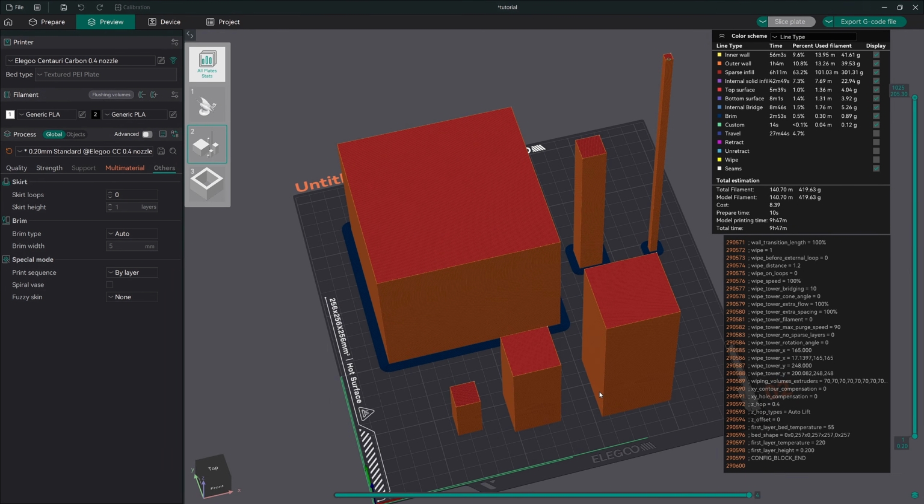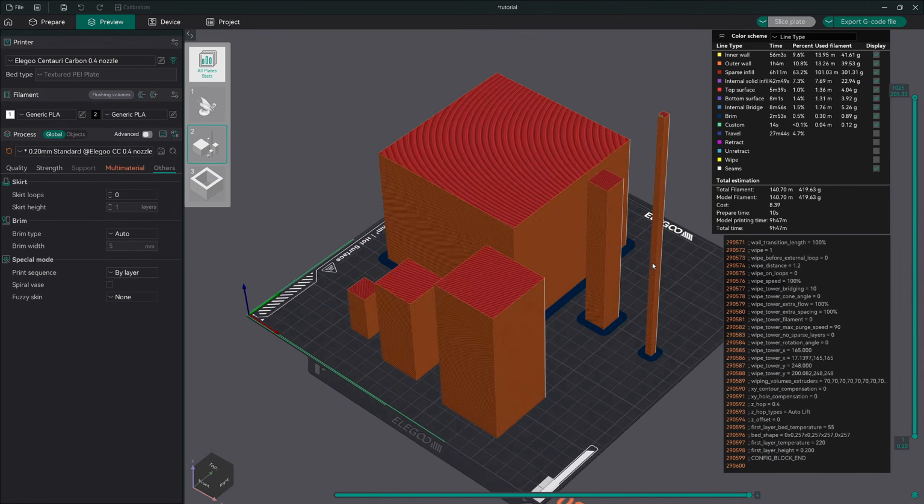However, the models on the top have a brim added, but for different purposes. This large cubic model has been given a brim because of the large flat surface area that it has against the build plate. The brim was added to prevent the corners from curling up or warping. However, you can see that these 2 skinny tall cubes do not have much area on the build plate.